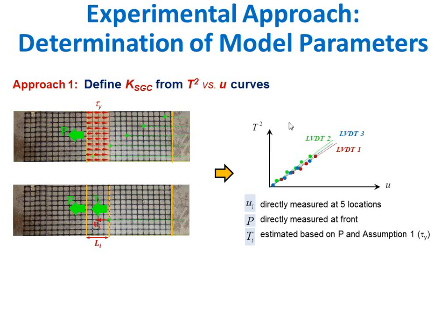Some others have investigated this even further, and they say this matters a lot when you're testing materials under unconfined conditions, but under confined conditions, even if the specimen is not that wide, it's the confinement that will prevent this necking. So I cannot give you a full answer to that, because I could only give it to you if we do the right testing. I could say that there is good evidence that this could be good enough if you test it in one direction and you minimize or prevent the necking. And in principle, you do that by adding confinement to the specimen.